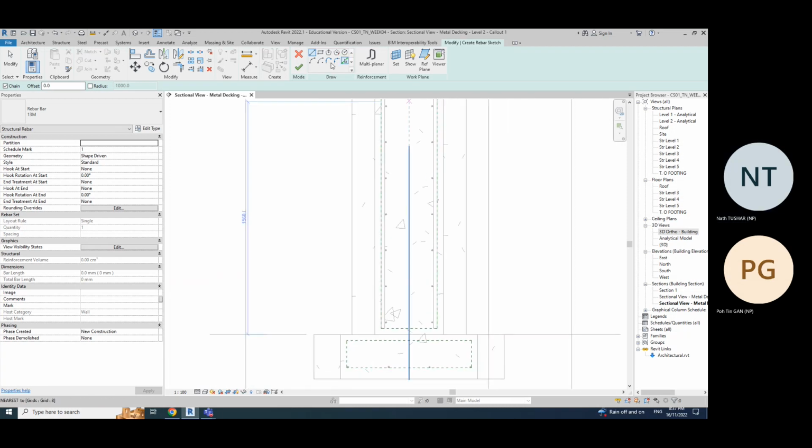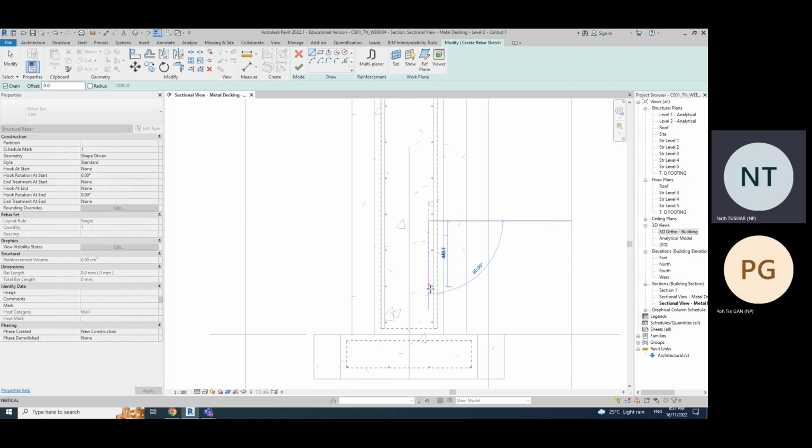Okay, now select this line. This line should be turned blue, and you can model your start point from this location somewhere here and go all the way down, something like this. Don't worry, first go down. We will rectify all those things in a moment. As soon as you come below this reference plane, one click, and then continue modeling in this direction till you reach somewhere over here. Then once you are done, click escape.